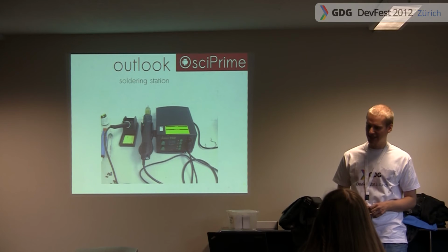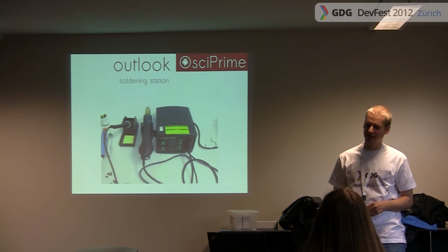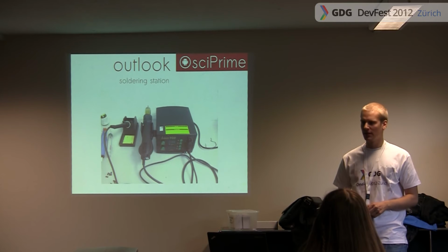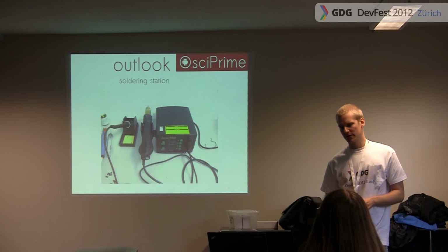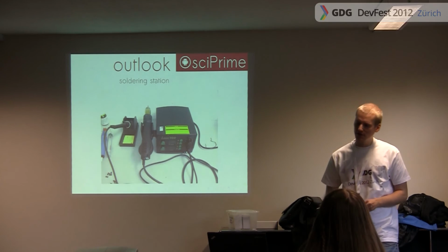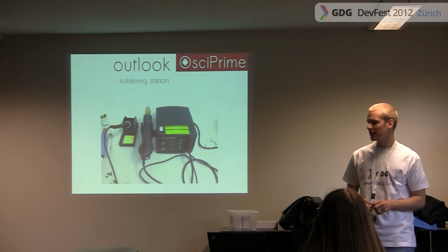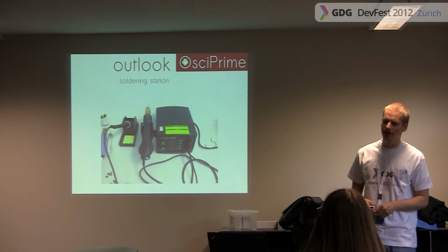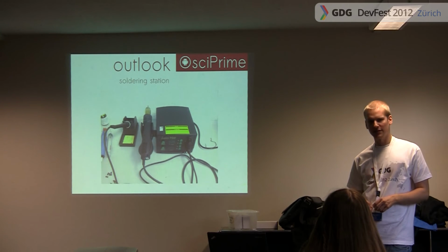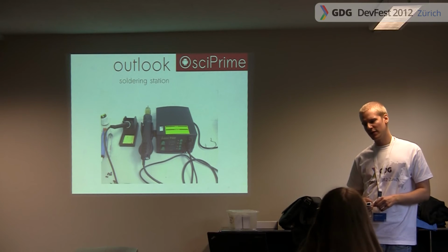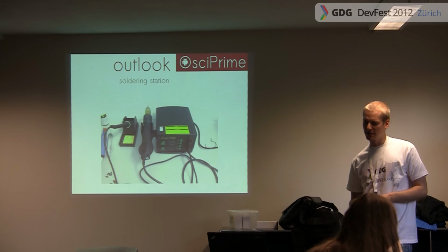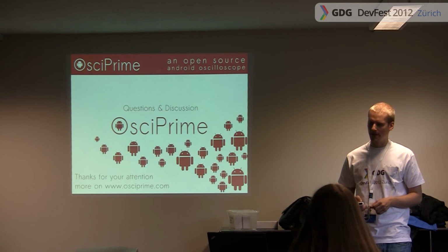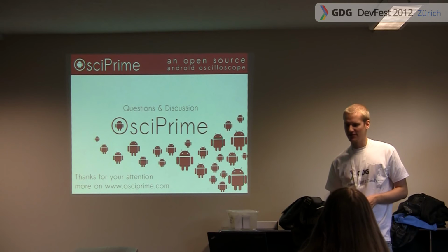What we also want to tell you is that you will need a soldering iron, especially if you need to repair something. Maybe a component is broken because you touched it while you were electrically charged or something like that. Soldering irons can be pretty pricey, but the one that we got costs only around 70 euro, and it even has a hot air gun. We use this for desoldering, especially if the component has, like you said, up to 100 pins. It's a pretty good technique to desolder the component. So that's it for the hardware assembly part.